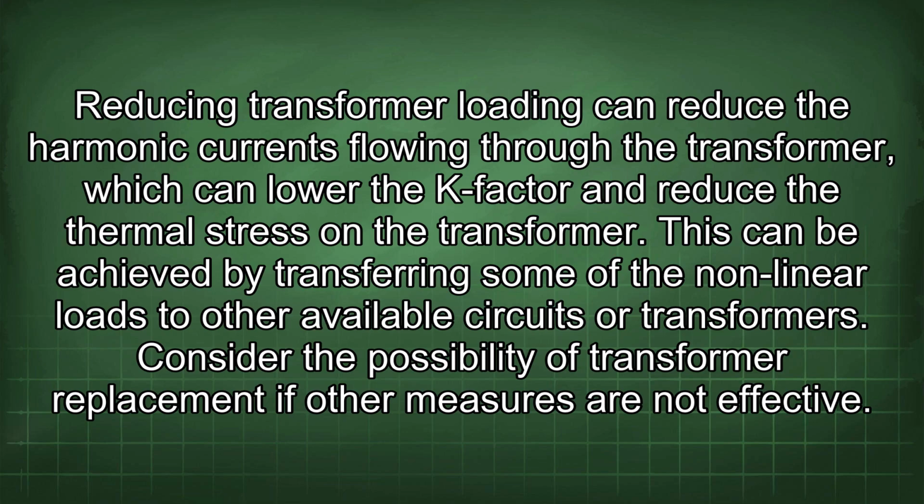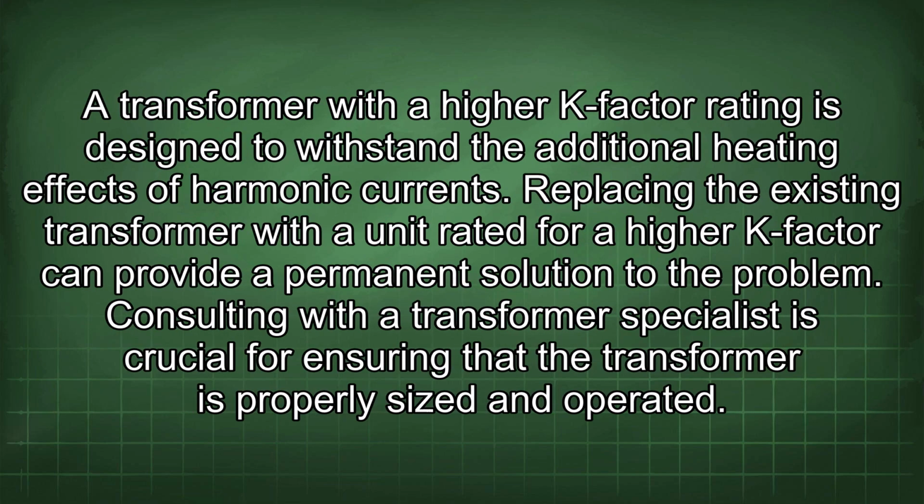Consider the possibility of transformer replacement if other measures are not effective. A transformer with a higher K-factor rating is designed to withstand the additional heating effects of harmonic currents. Replacing the existing transformer with a unit rated for a higher K-factor can provide a permanent solution to the problem.